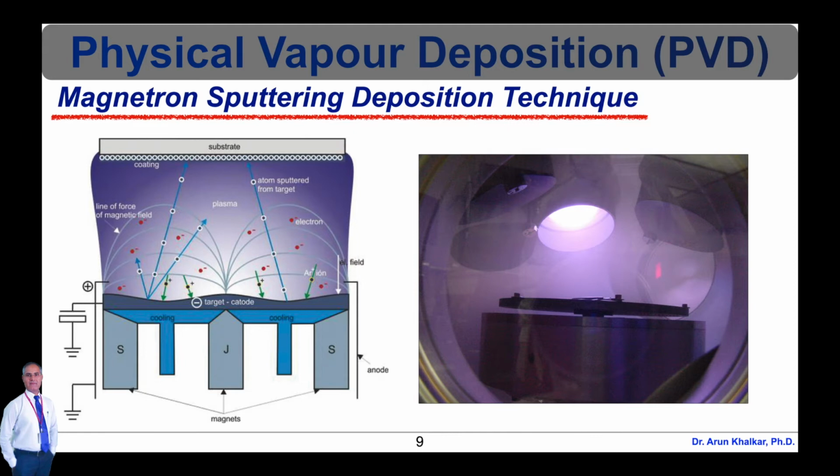After base pressure has been reached, the sputtering gas, which comprises the plasma, is flowed into the chamber and the total pressure is regulated, typically in the millitorr range, using a pressure control system. To initiate plasma generation, high voltage is applied between the cathode, commonly located directly behind the sputtering target, and the anode, commonly connected to the chamber as an electrical ground.